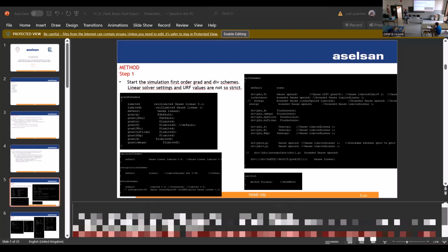That's why you shouldn't switch it on if you are not using transonic. The consistency switch, actually, means the SIMPLEC scheme that you are using. In that way, you're gonna add the off-diagonal terms to the equation.